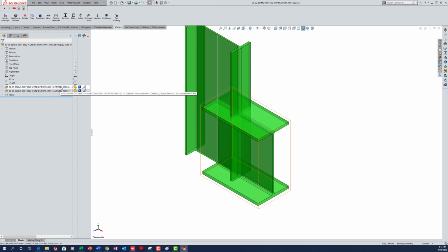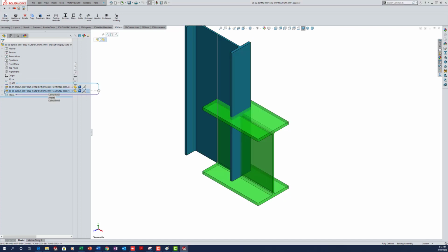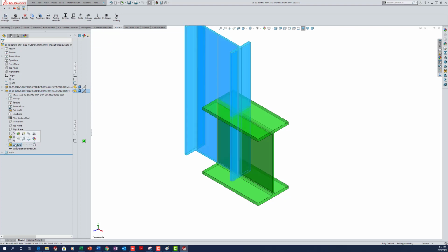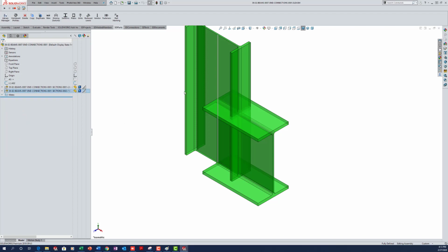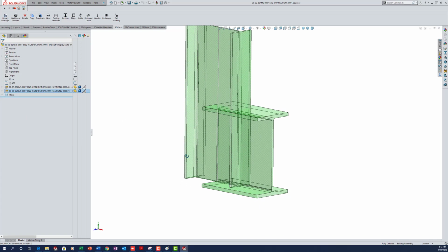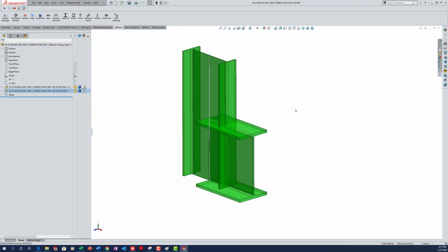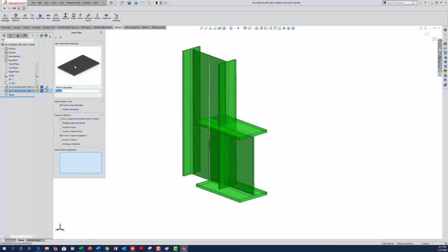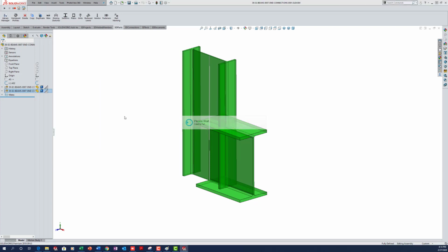So we have sections 1, the beam, sections 2 is the column. The feature for sections 2 needs to be renamed Bolted 1. This will allow the insertion process to resize this column. So now we'll need an end plate for this. Again, under Parts, we'll go to Plates. And we'll just allow this blank plate to go in as a non-envelope and insert it at the origin. Tick OK.